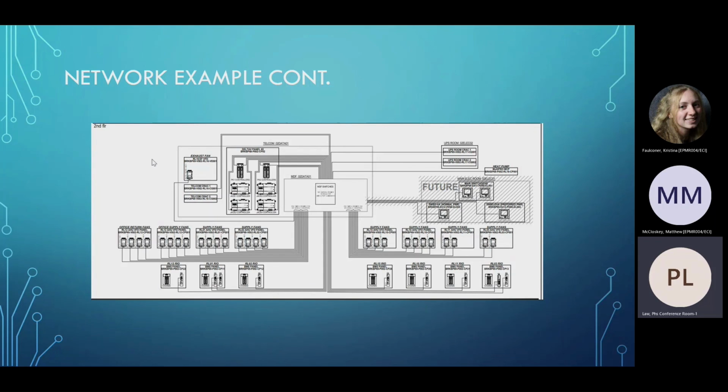The Jace converts it to Modbus, comes out of the Jace, back into the switch. Then from the switch as Modbus, the PKs can read that. PKs cannot read BACnet, so it's really not a problem. They just won't see that information.